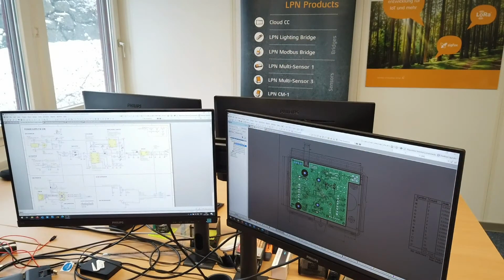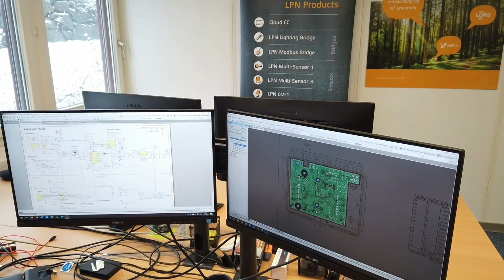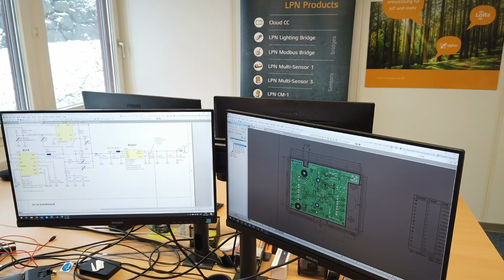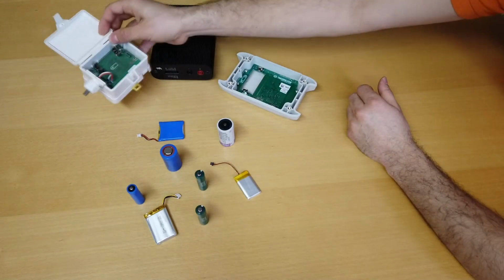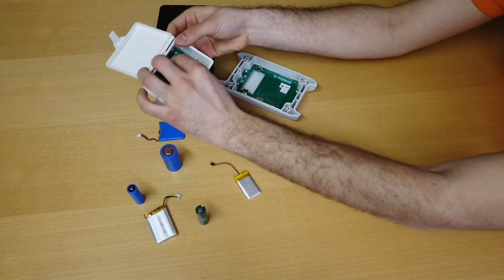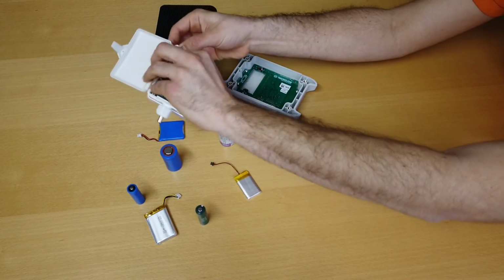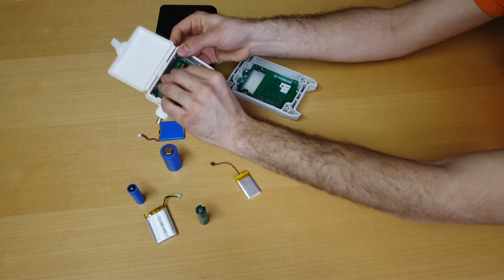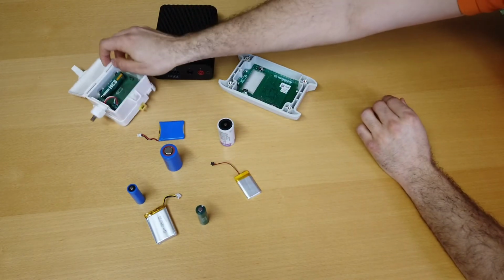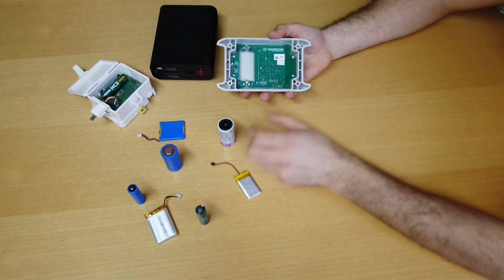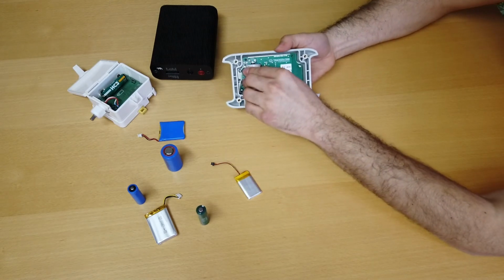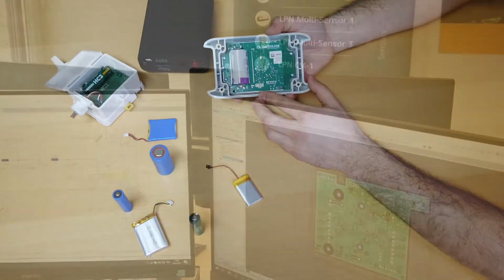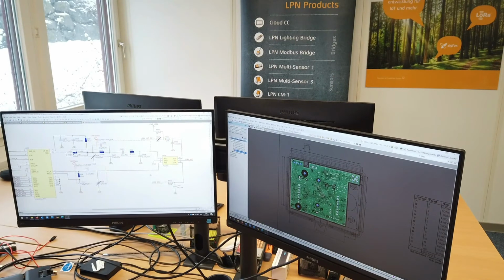We recommend you calculate and build a device consumption profile as precisely as possible. Take as many variables into account, like battery self-discharge, temperature profile, and so on. It is important to know that not all batteries are suitable for all products. Take care about not only looking at the datasheet, but also making measurements with the battery, discharging them, or for example, try to simulate them.